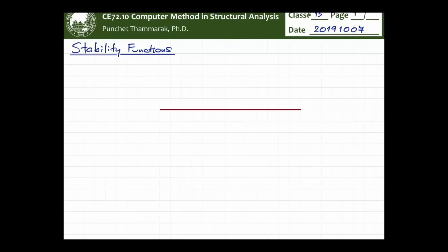So that's what we are going to do. We will just apply the rotation or the displacement degree of freedom one at a time, and find out the corresponding forces and moments required to maintain the system in the given shape that we want. Okay, so let's take a look together.